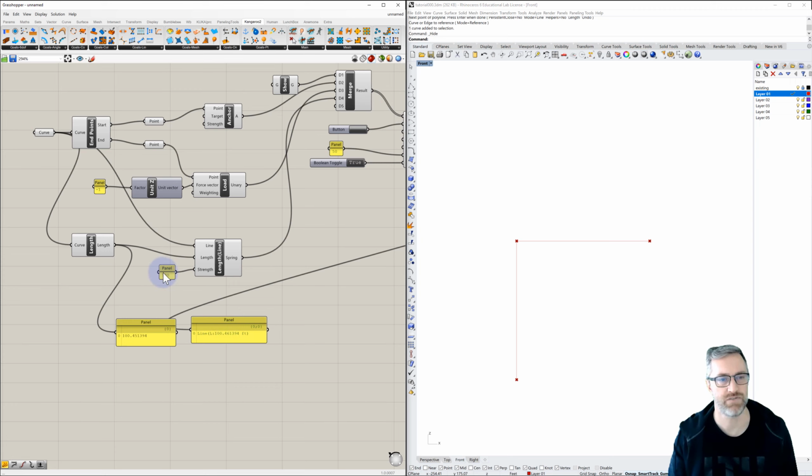So if we change the strength of our line, of this constraint, let's set this to 10. We'll see what happens. We see that this dimension changed. Let's set this to 1. We see that that dropped even more, because what we're doing is we're simply applying a downward force to this one point. We can even hit reset, and we can see the way that that's playing out.